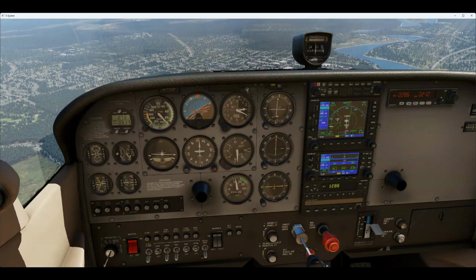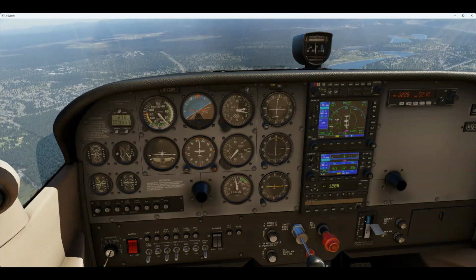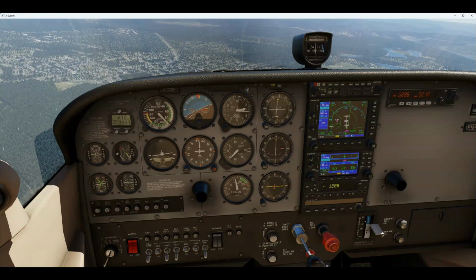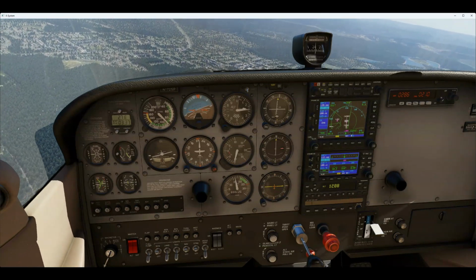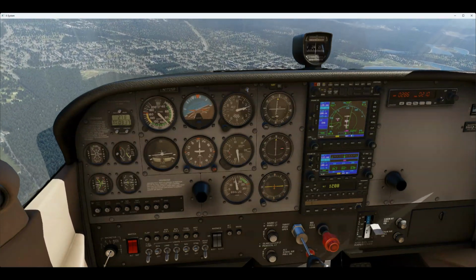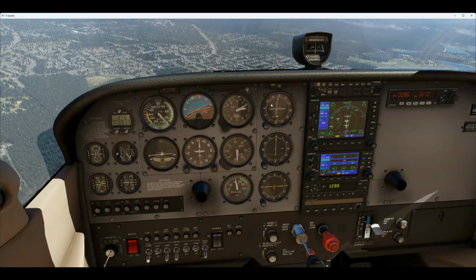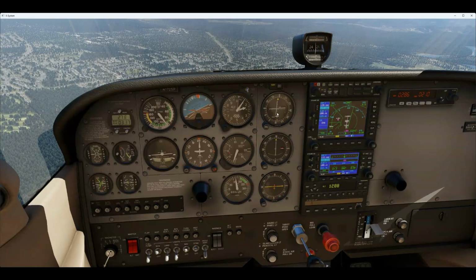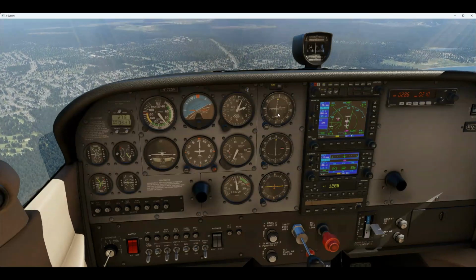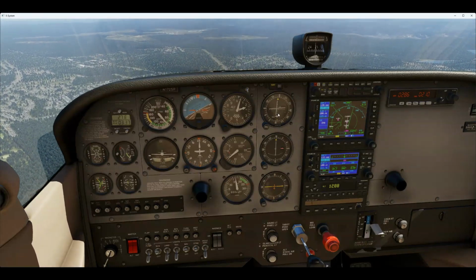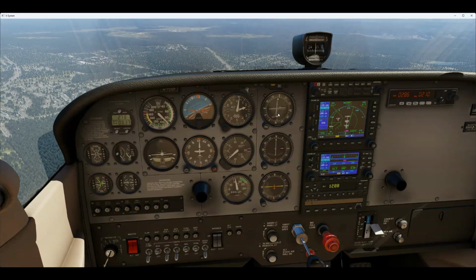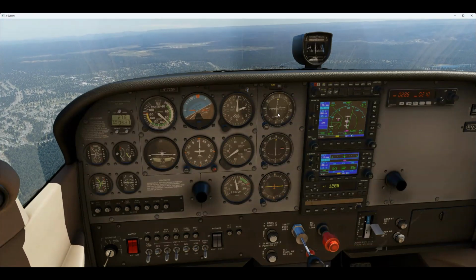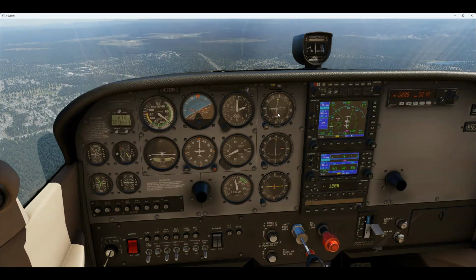Okay, we're back on glide slopes, and now I want to arrest that descent a bit. I want to be tracking a little bit more to the left. One thing to be aware of is that the CDI will quickly get out of tune unless I'm tracking correctly. So I'm on glide slope. It's actually telling me to fly up a bit, which makes sense because we calculated we want to do 400 feet and I was only about 700 feet there. So we'll arrest that descent rate a bit.